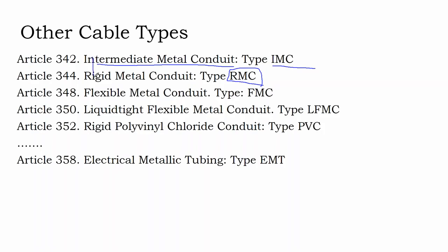In the solar industry, we're not trying to have a lot of money spent on our conduit, a lot of protection on our conduit, and we're usually going in with EMT conduit. But you have to check the weather ratings to make sure that your fittings are rain tight rather than just indoor. Whereas rigid, those fittings are usually always watertight, also much more expensive.